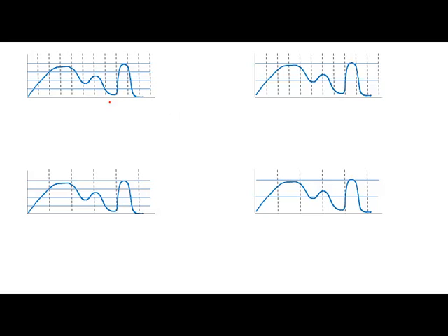So here I'm showing the same analog signal. On the x-axis you have time, and this could be microseconds. These dashed lines could show microseconds here, and the y-axis is the input voltage, which is an analog signal, and this top line is your VDD. Now, if you're using a device that uses 5-volt VDD, then this would be 5. If you're dealing with a 3.3-volt device, then 3.3 would be the upper voltage level.